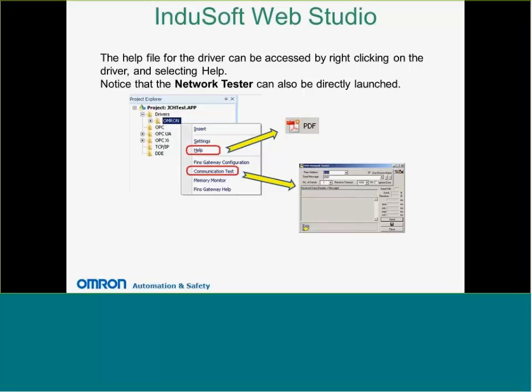Once you've inserted the Omron driver, there's a couple of things you can do. By right-clicking on the Omron driver, you can launch the help PDF file. You can also directly launch the FINS network tester that we just looked at. So in Web Studio, we've built a hook into that testing tool directly.